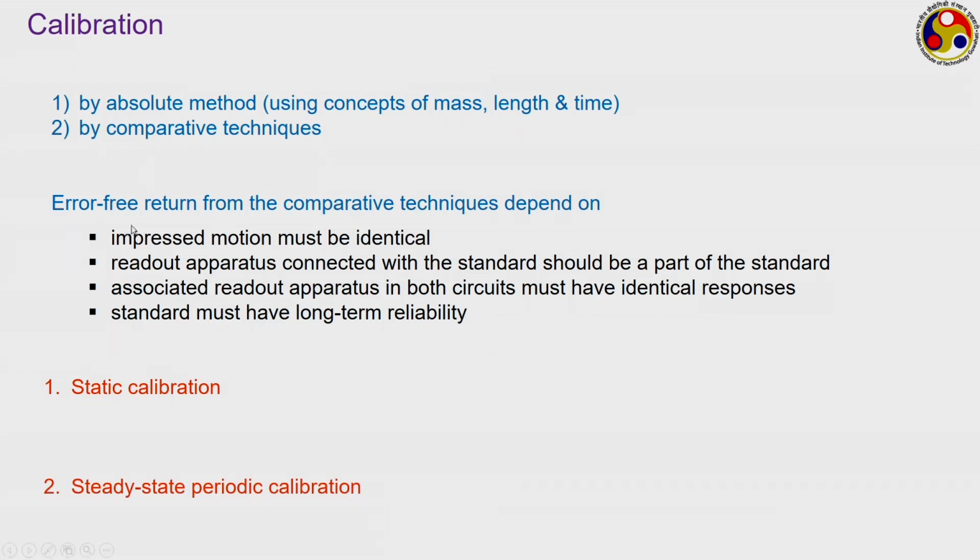In case of static calibration, we can have 2 kinds of methods. One is plus minus 1 G turnover. That is a very simple situation where particularly low range accelerometers are calibrated following this way, where we just rotate the accelerometer upside down.